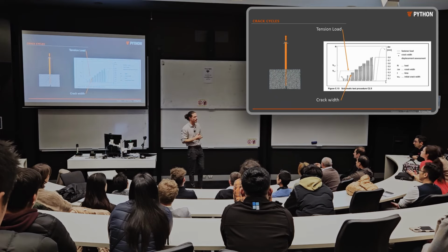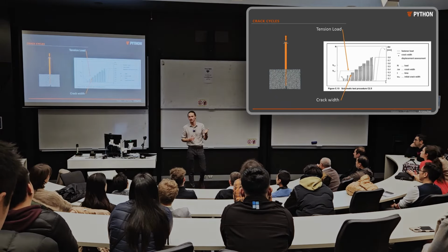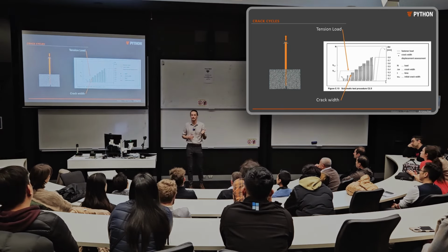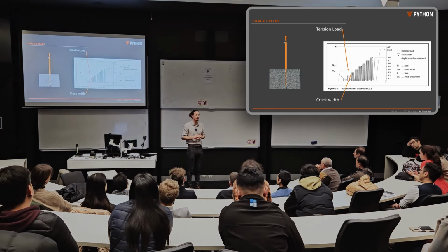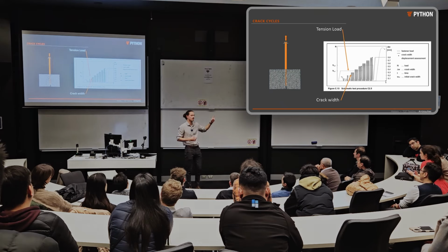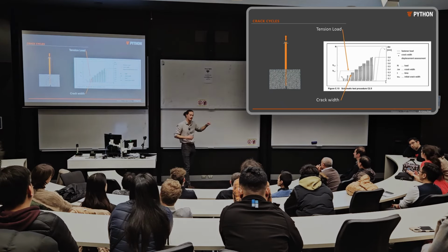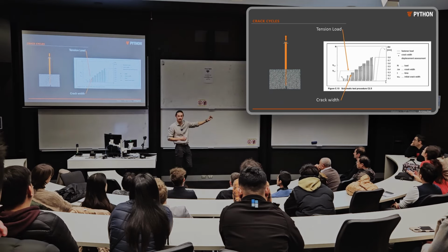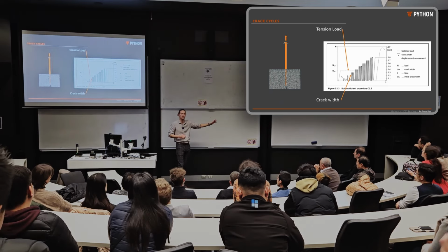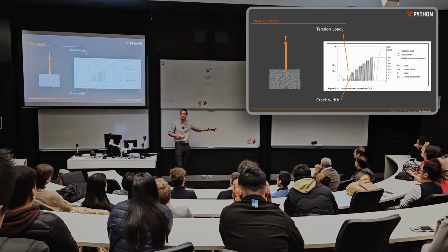Fantastic. Where it really has implications is if you're doing critical infrastructure, if you're looking at a hospital, if you really need your anchors to work in really large return period earthquakes, fundamentally, C2 is allowing for a 90th percentile 475-year return period earthquake in LA. And so that is a point of concern and something that I think is important to be aware of if you are looking at those critical infrastructure projects.